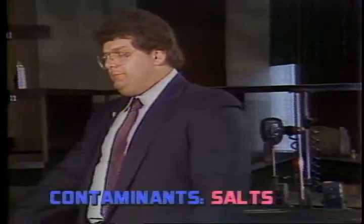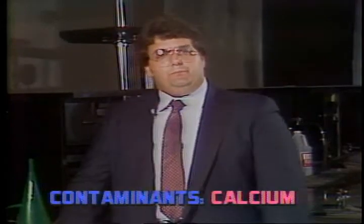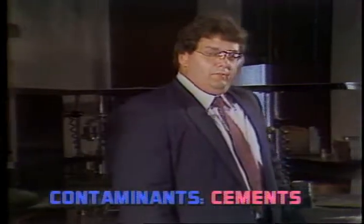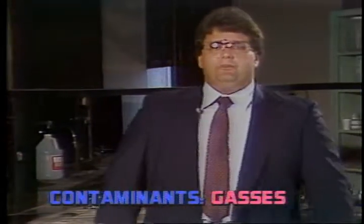We've already talked a little bit about salts and how they contaminate the mud system. We've also talked about sodium, calcium, magnesium, cement that's used to cement casing and for solving some hole problems, and even some gases that are encountered during the drilling procedure. All in all, for any one of these particular contaminants that we encounter during the drilling process, there is a specific product that can be used to help control or minimize their effects.